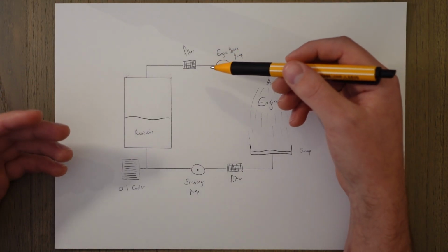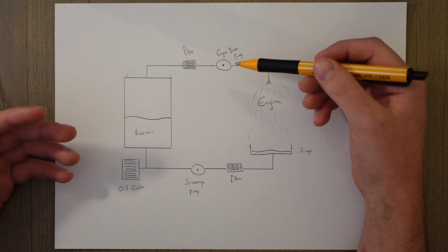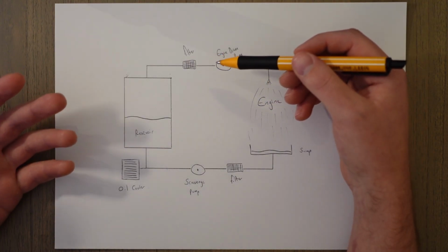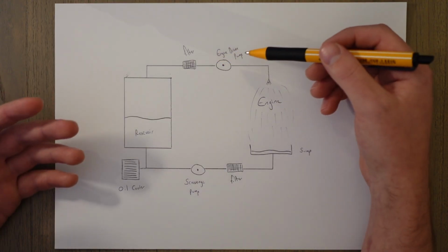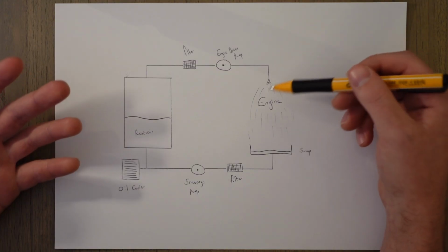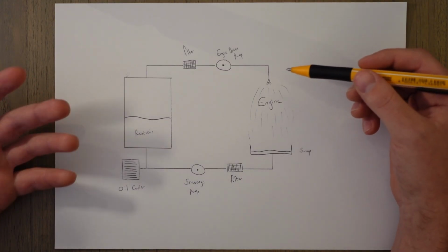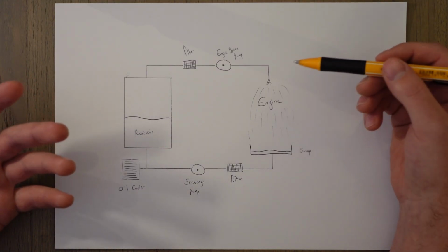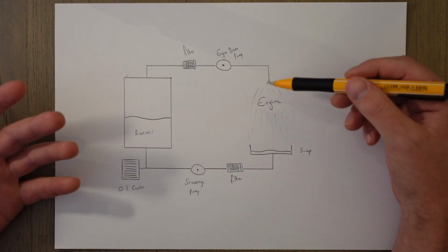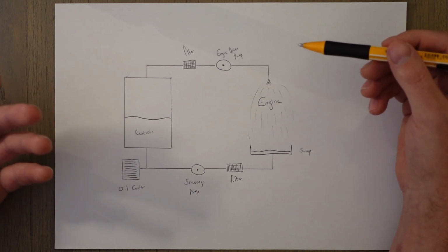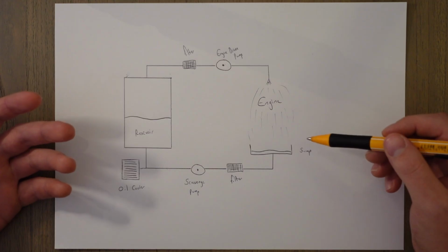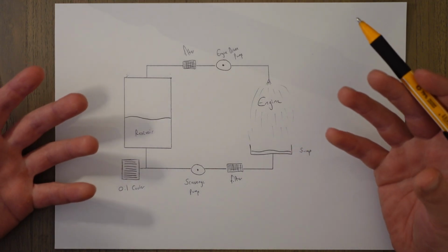These filters are replaced periodically, and it's much cheaper to replace a filter than a pump, which is why these filters are in place. So after the pump, the oil is delivered to the engine components that need it and sprayed over them essentially. These components are mainly the crankshaft, the camshaft, and the pistons. And after the oil has done its job of cooling and lubricating, it naturally runs down the engine because of gravity and collects in the sump, which is like a bucket underneath the engine.